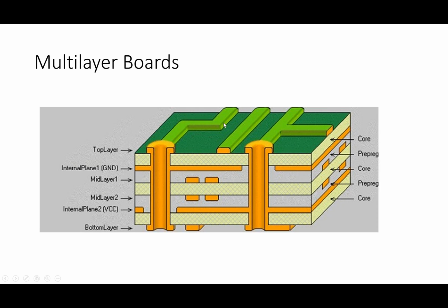you know from taking fields, okay, if there's a voltage on this line, let's say for the sake of argument that this wire right here is at 100 volts, and in this particular case, this one is actually grounded. I see that this is connected to the ground layer. Because this is the ground layer and it's connected physically to this plated through hole and then to this line, this is a grounded line. Let's say this one right here was at 100 volts. So if there's 100 volts here and ground here, there's an electric field between those two things.